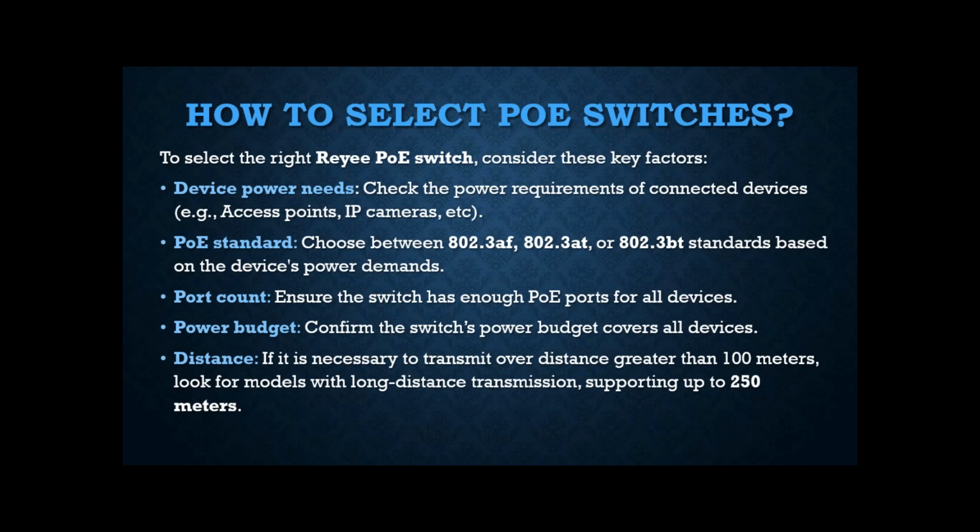We have to take into consideration as well the port count. So ensure the switch has enough PoE ports for all devices. The power budget: confirm the switch power budget covers all devices. And the distance: if it is necessary to transmit over a distance greater than 100 meters, look for models with long distance transmission supporting up to 250 meters.